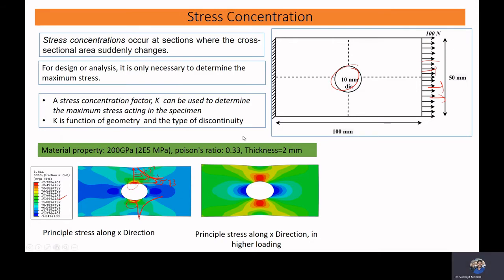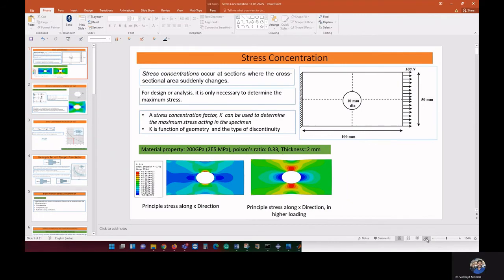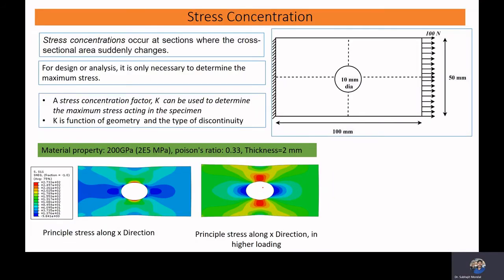Okay, so here what we have seen is the change in the stress if we have a plate with a circular cutout and we apply the load. This circular part will be elongated and it will look like an ellipse. That's fine. And here there will be high stress concentration, and if you go away from here, you'll observe the magnitude of the stress varying like this.